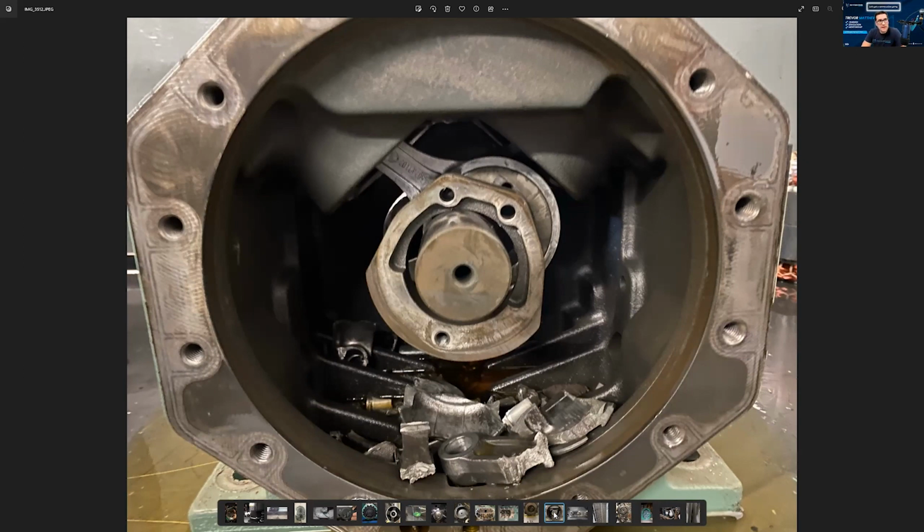Oil is another one that is hard, because if you don't have a sight glass, even if you do have a sight glass, oil is hard even on a supermarket system when you don't really understand the full dynamics of it. The viscosity is so important. That's something you need to start learning more about, understanding oil. A lot of people don't understand. I didn't understand it while I was in the field as well as I should have. It takes a long time to understand where that oil is at. If the oil's too hot, it's not good. If the oil's too cold, it's not good. So there's a fine balance when you're dealing with loss of oil issues. That's for sure. Happy medium.